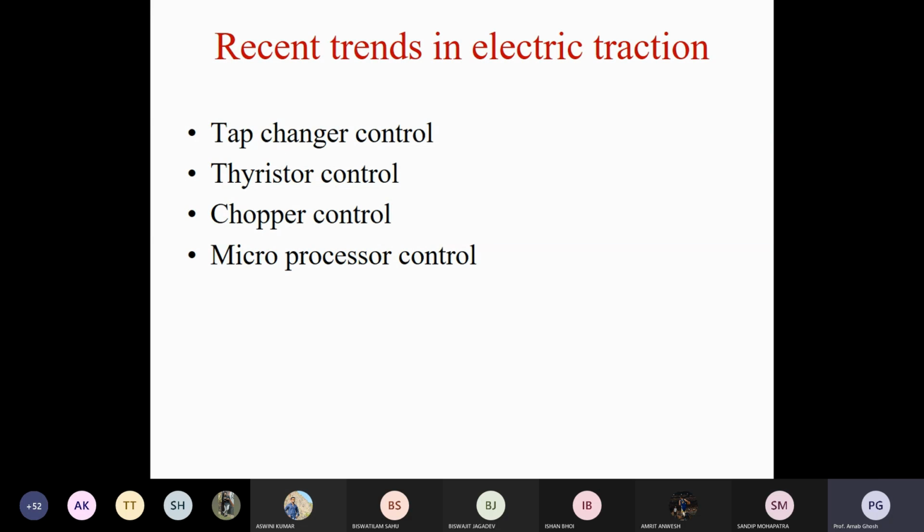That's why for mainline transportation, the auto transformer you are using has the tap changer. In mainline transportation, I think the auto transformer is not there, maybe. In that case the normal transformer is there. After that transformer you just add one for the speed change of the armature of the traction motor. So in that case the tap changer is on the primary side, but in a normal city ride the tap changer is placed on the secondary side. That's the reason. Then the chopper control.